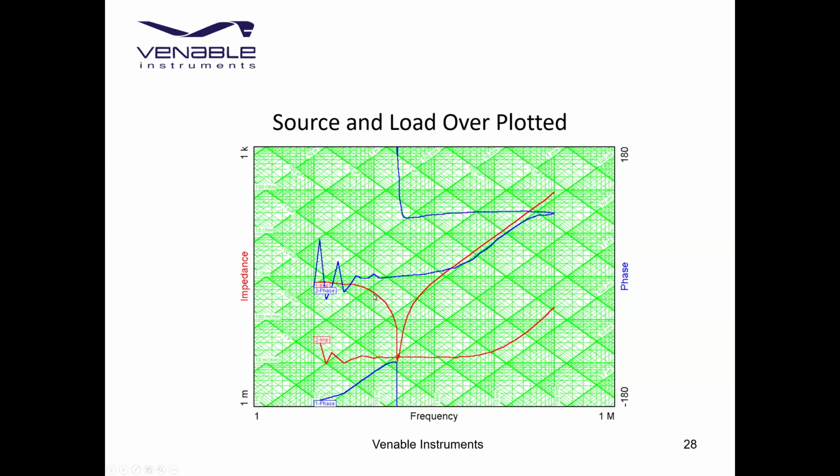We actually created an input filter for a power supply and made it a high enough Q that it went unstable at this point, where the red notch crosses the lower plot of the source power supply. The upper one is the power input of the power supply being driven with a filter on the front end of it. So it definitely does happen. If you try hard enough, you can make an oscillator out of that.